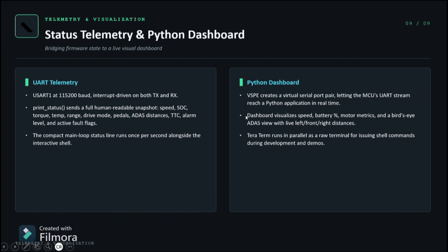And coming to the Python dashboard. We have used VSPE, which creates a virtual serial port pair that lets the MCU UART stream reach the Python application in real time. The Python dashboard will visualize speed, battery percentage, motor metrics, and the bird's-eye ADAS view with live left, front, right distance. We will be seeing this left, front, right in the demo video. Up next, the demo.